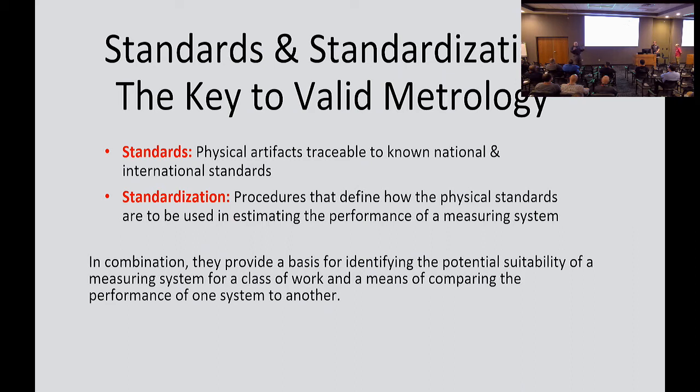And how do we use those artifacts? Well, we need to have some standardization, some standard procedures. In most cases, we don't cook these up ourselves. When we do cook them up ourselves, we always seem to make mistakes and we look stupid. Fortunately, ISO, ASME, and sometimes our manufacturers give us a standard that says, take this artifact, here's how you use it. That's how we go to work on all our CMMs and vision systems. Put those two things together and we can feel pretty good about our results.